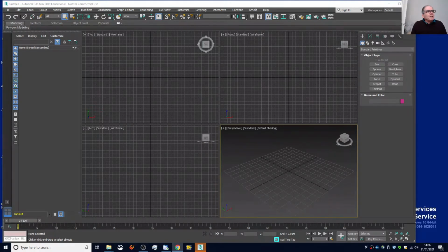Why? Because linking allows you to fully control how the individual parts move around, and you can animate each one with certain constraints with absolutely no problem. While grouping turns several objects into one single object, so when you do animation editing, you can only apply the same animation, the same settings, to the whole group, and that's where the difference is.